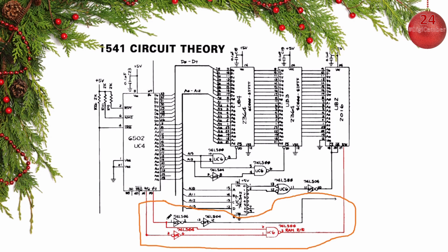You can see this is inverted, so that the write is the one that is going to be low, and the Phi2 clock is high. So when both the read-write signal is active and the Phi2 clock is active, you get a signal here that will select the read-write on the memory. So that is of concern. We might have to include this trickery down here.